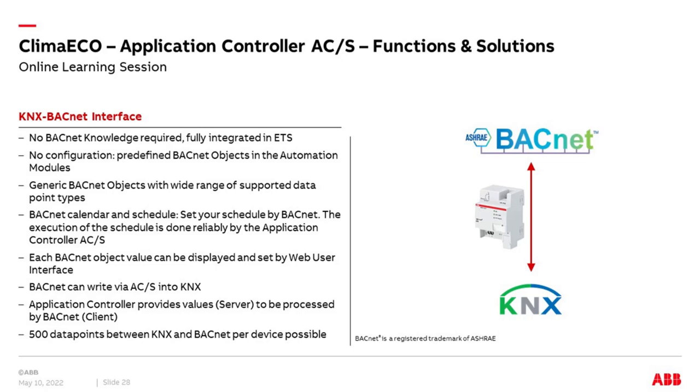Yeah, what can you do? Bidirectional communication, as mentioned. So BACnet can write into KNX easily, or you send a value, a status from KNX to BACnet. Both directions are possible. You can parameterize this in the ETS, in which direction you would like to go. If we send or deliver a value from KNX to BACnet, what does it mean?